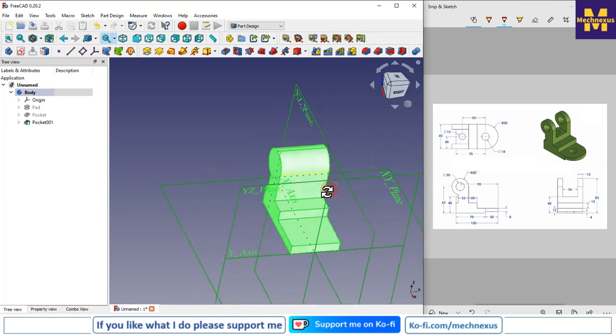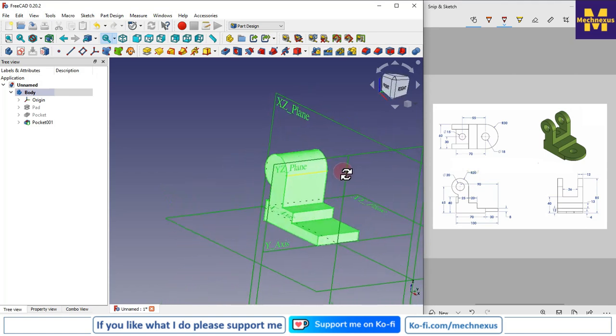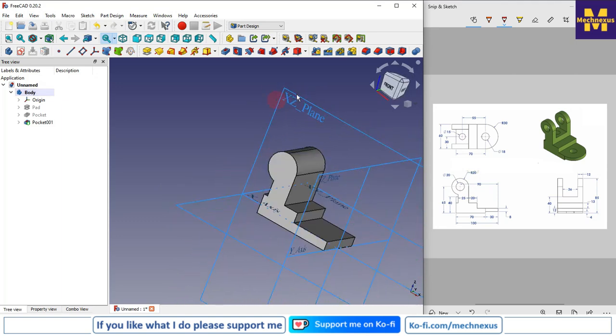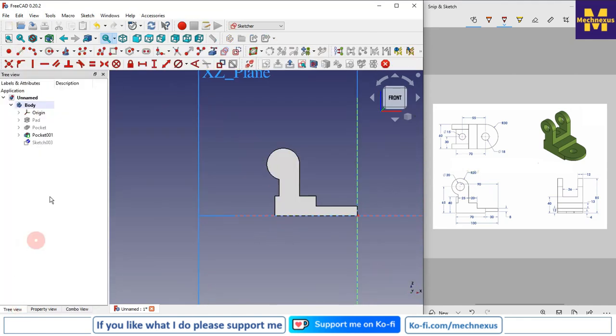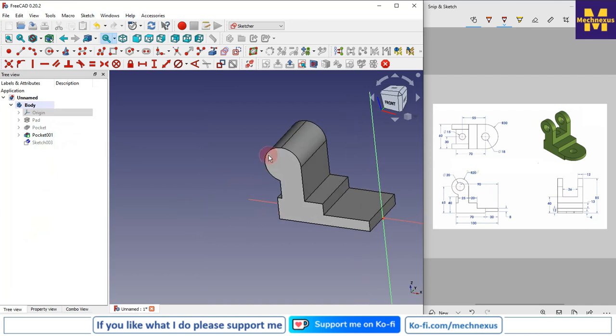So the best modeling practice is that you imagine the part in your mind before you actually create it in the software. Now I will select this mid plane and create a sketch, and I will go to the tree view. Now we can see that the cut is 36 and from the bottom it is 40.